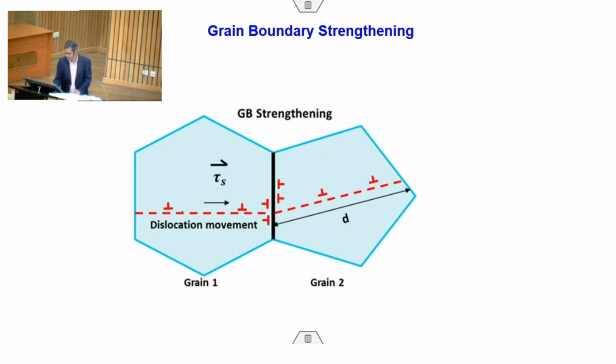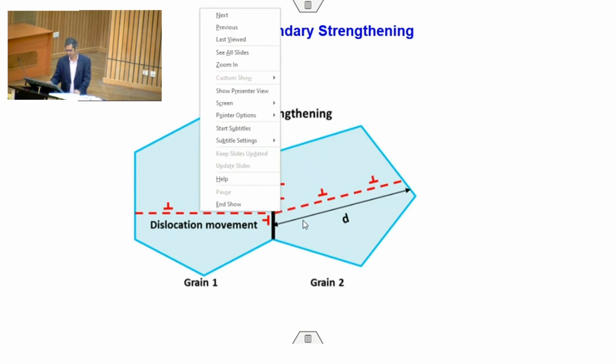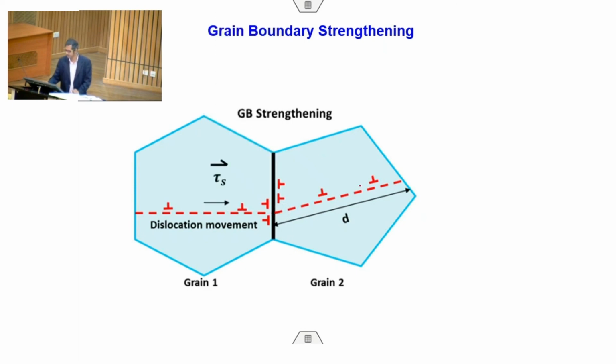See, this is a two grain model. You can see this is the slip plane. Dislocations are moving like this, then reach the grain boundary and pile up. Correct? So, in order to start dislocation motion in the other grain, enough stress should be applied so that the other grain starts deforming and dislocations start moving. Or it should be that the two grains have the same kind of slip planes at a certain deviation from the angle. It was like this, correct. But normally that does not happen. Slip planes will not be arranged that way.